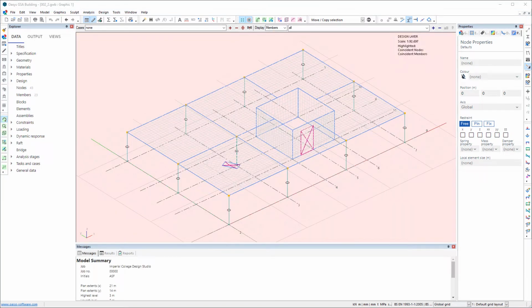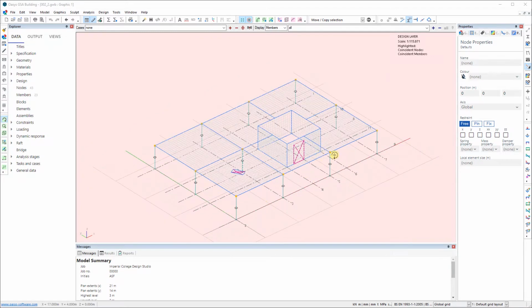So continuing on, this is where we got to at the end of the last video. We've got our sub-model here, essentially a floor and the columns and the walls below it. So now we want to take this and make our multi-story structure. Again, I'm just making this up, but you can clearly see how it can apply to the design project that you're all undertaking. I'll also be adding in an inclined column as well. So again, to give you an idea of one way at least that could be done. So we want to copy this up several times. And I'm going to assume that the floor-to-floor height's exactly the same to make it easy for myself.